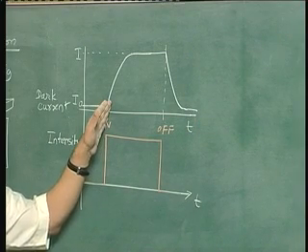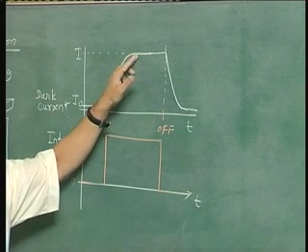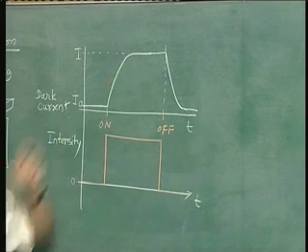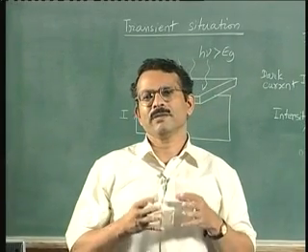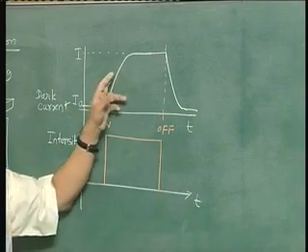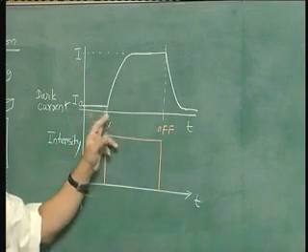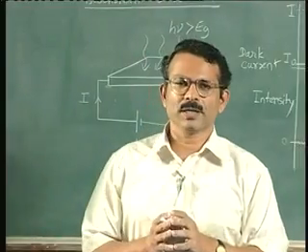The excess carriers are generated and their concentration starts increasing and then reaches a steady state after some time. Now it is this time that is of interest in the switching performance of devices. We will show that these delays associated with the on transient and off transient are related to an important parameter called the lifetime.